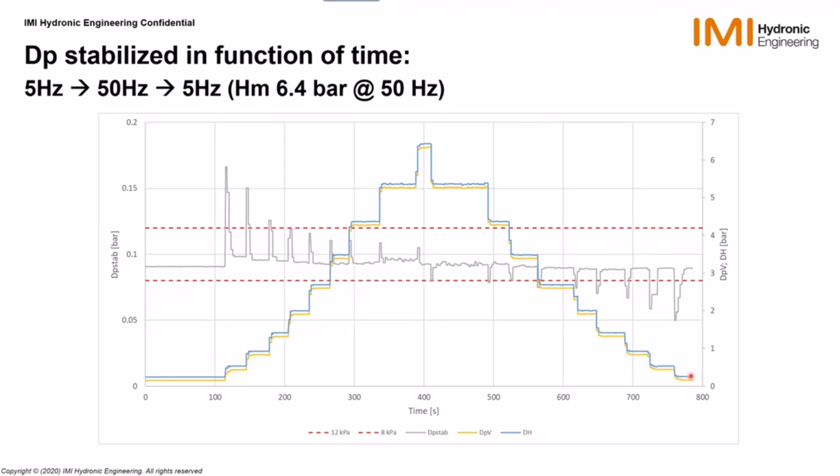We have, of course, tested the EDPV. I don't have such good curves right now. We need to extract a little bit more data. But I can tell you there is nothing comparable there. The EDPV of Belimo is extremely slow. While you can see that we are controlling within something like 5 seconds-ish, the DP back to its set point, 5, 6, sometimes seconds.